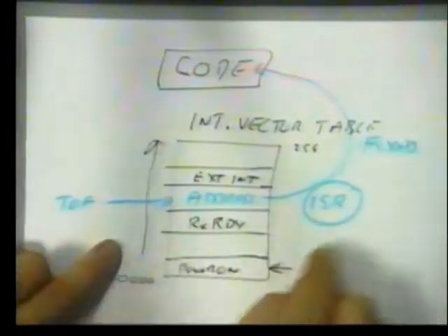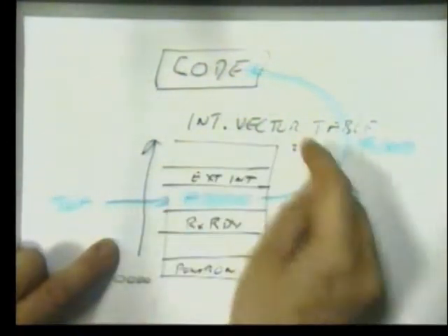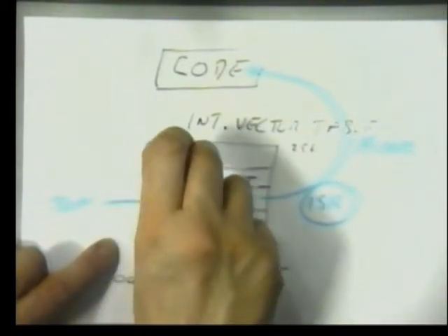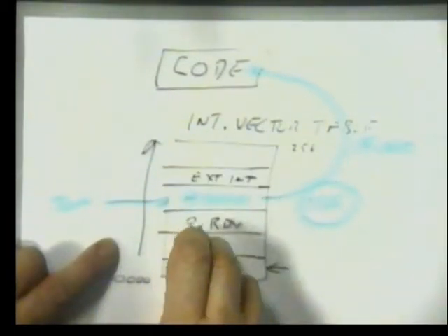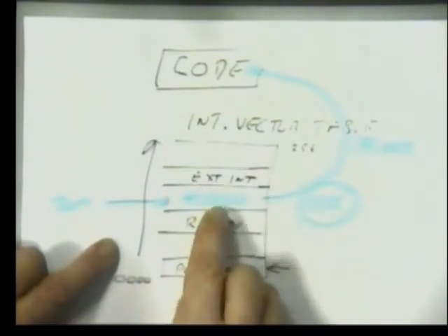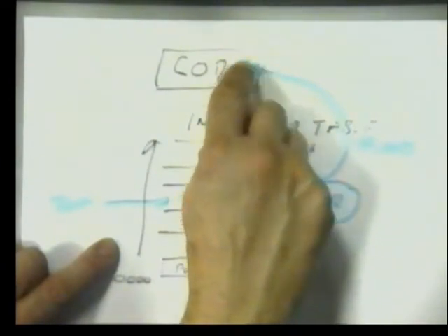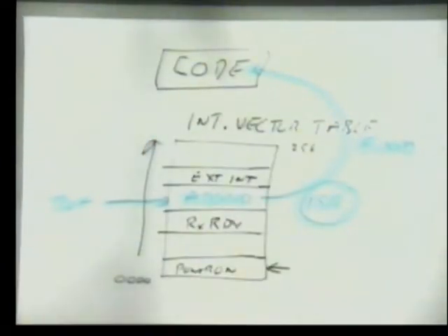So what happens is, an interrupt occurs. This is a signboard. It's in a fixed memory location. We go to the specific point in that table that tells us what to do next. There we will find an address which our program, that's your job, you have to put that address in there, that points us to the code space, and there that will then hold the interrupt service routine.